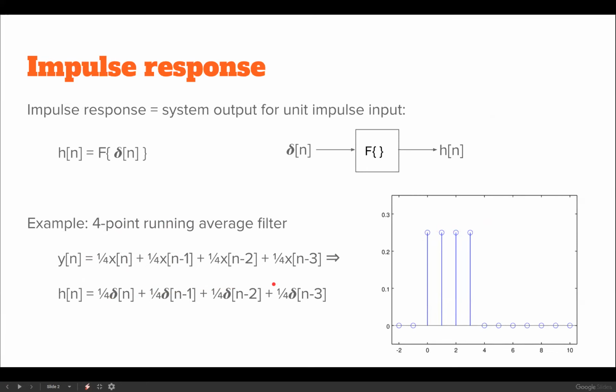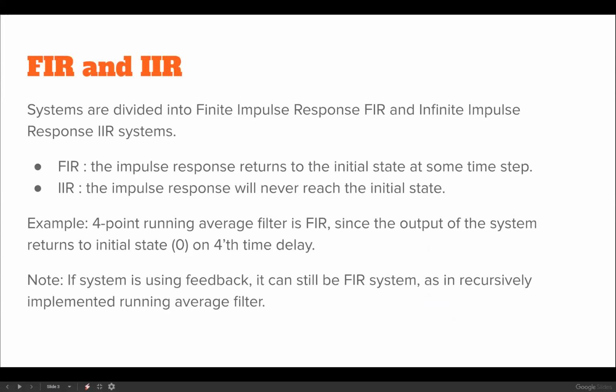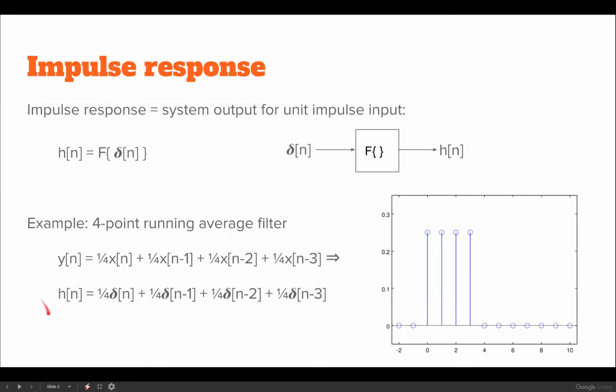It can be directly calculated from the difference equation, but on the other hand, if you have an infinite impulse response system, then this does not work anymore. You cannot take just this h of n and use these calculations. What you need to do basically is to have some feedback in the system in order to calculate it. But that comes from last week's systems. We had these systems with feedback.